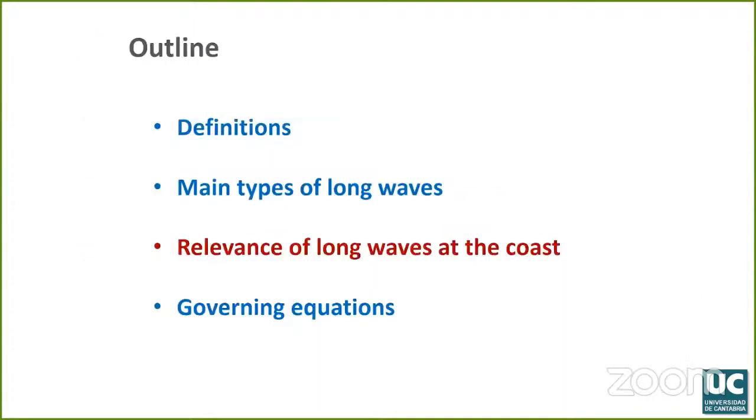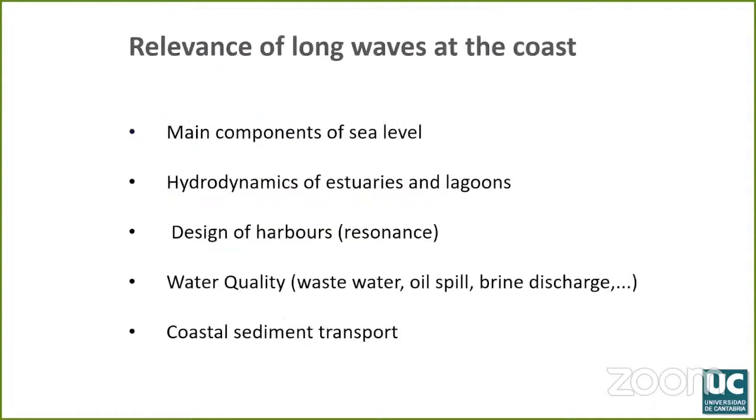Following this quick review, you can understand why long waves need to be studied. However, let me give you some reasons why these waves are so important. Long waves are the main components of sea level. They define the hydrodynamics of estuaries and lagoons. We have seen that they have to be taken into account when designing a harbour due to resonance issues, and long wave-induced currents need to be assessed in order to study water quality and coastal sediment transport.